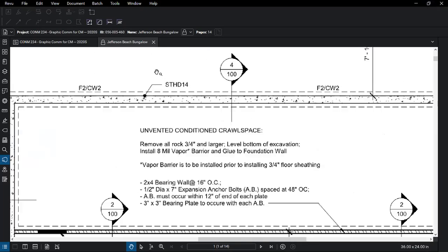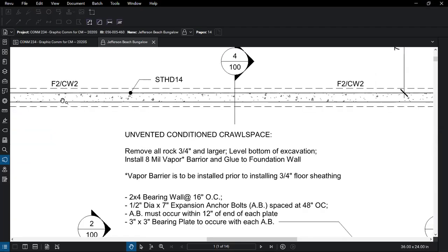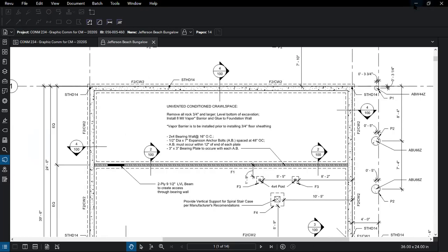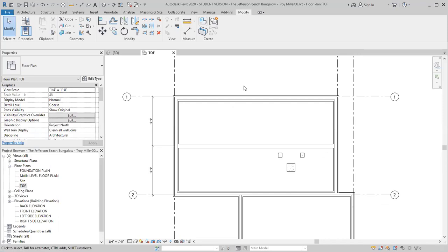So at this point on a standard foundation drawing, we show our foundation wall using standard object lines. But the footing that's below a foundation wall in a T foundation system, we end up changing that to a hidden wall line type. So in Revit, they make this actually fairly simple to do.